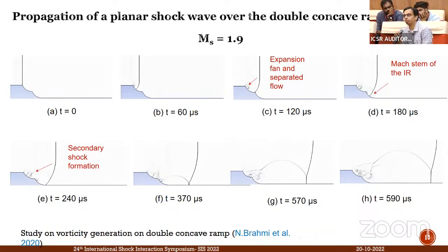Yes. So when you say supersonic flow, I really doubt that. And I will also tell you why I doubt it. In the lab frame, the solution for the shock tube problem is that at infinite shock strength, the Mach number downstream of the shock in the lab frame is 1.34. That's right. So something to consider.